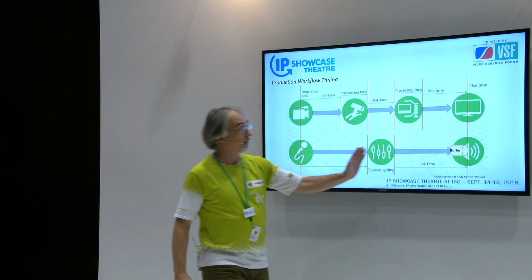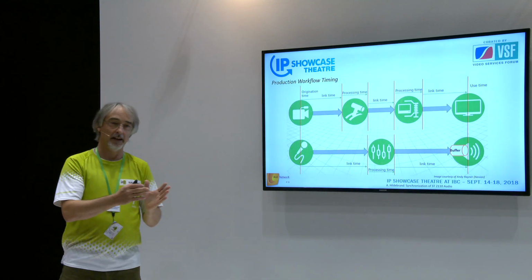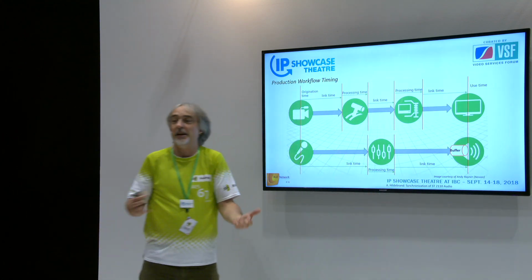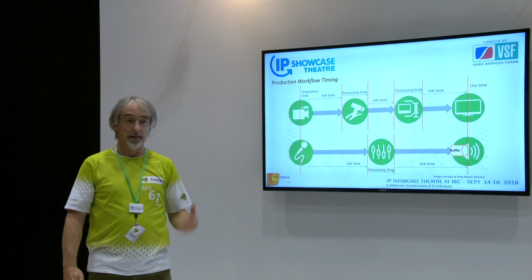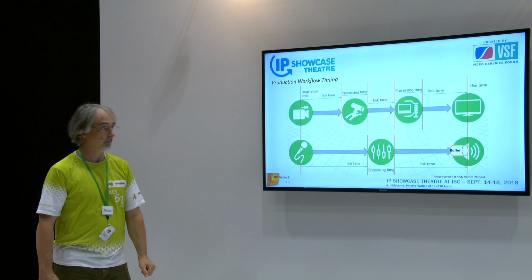So this speaker device needs to have a suitable buffer to hold up the incoming packets and align them for further processing, this time's playout, to be aligned with any other stream, audio stream or video stream. And this all goes by looking at timestamps and wall clock time.